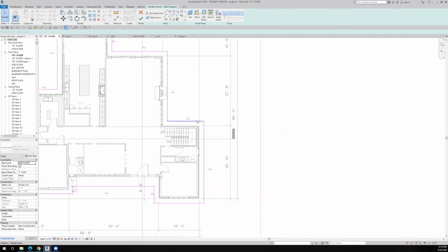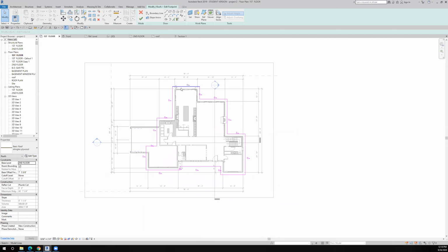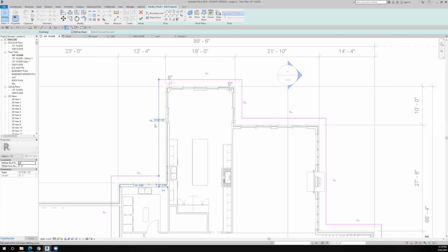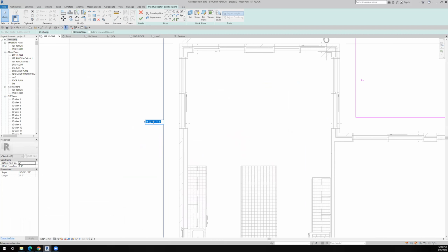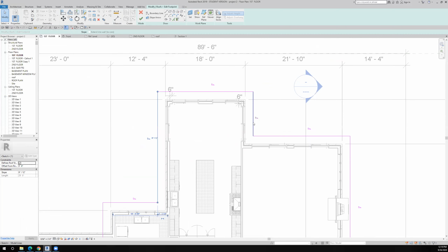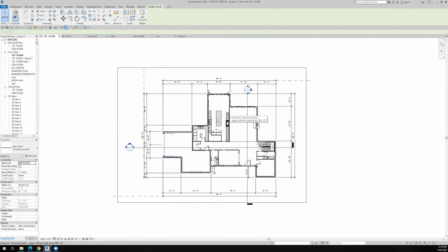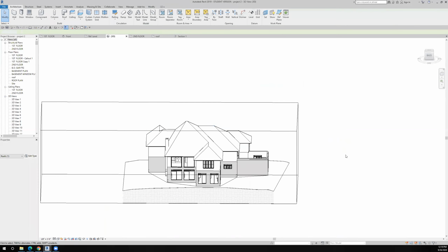I'll be able to see it in any footprint. And let's see what the slope of this guy is. Look at that. Somehow it changed to 15 something 12, but I think we were doing 9/12 around there. So what's this side? 9/12. 9/12. Okay, that was just a good eye on my part that somehow that particular slope changed. I don't know how or why it did, but you can see now that looks a lot better.